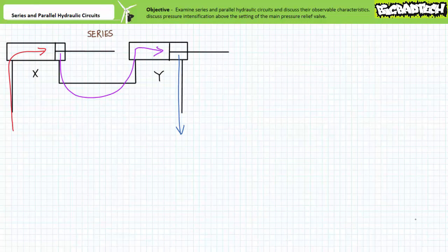Furthermore, the series relationship synchronizes the stopping of both cylinders. Given both these cylinders are double-acting, cylinder X cannot extend if outflow from its rod end is blocked, nor can cylinder Y extend if fluid input to its cap end stops. Anytime either cylinder stops moving due to reaching the limits of travel, or perhaps opposing a force in excess of that capable of being generated, it serves to simultaneously halt movement of the other cylinder.